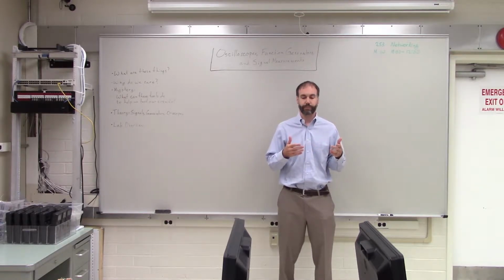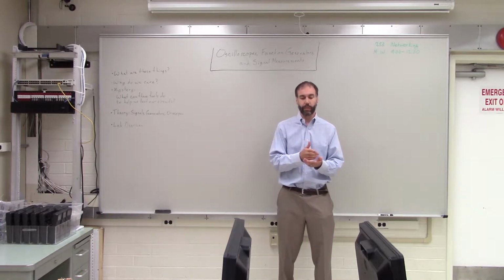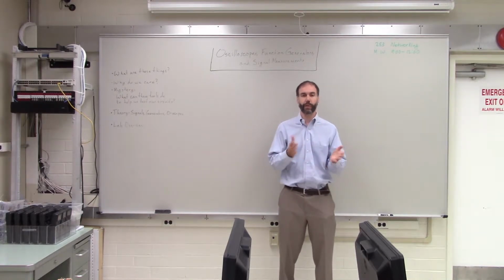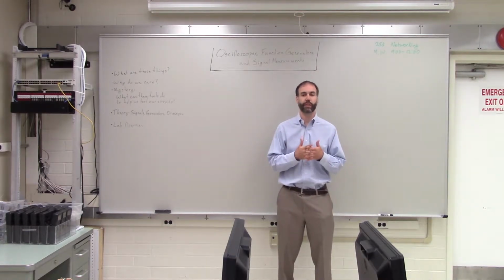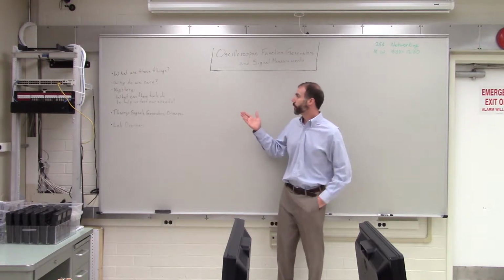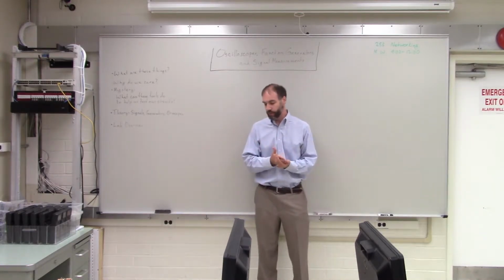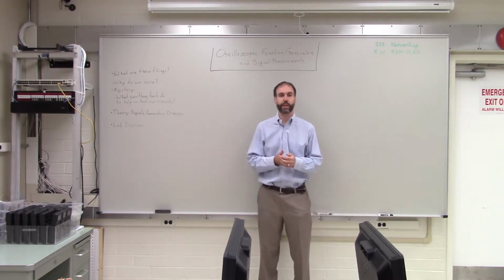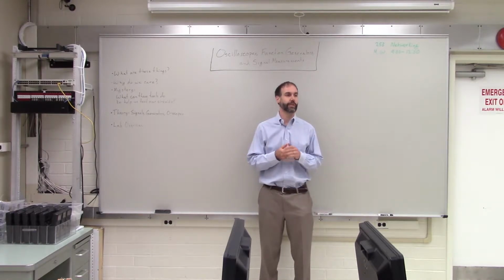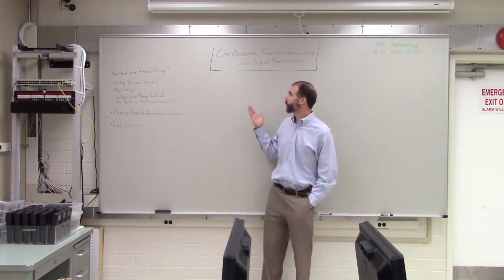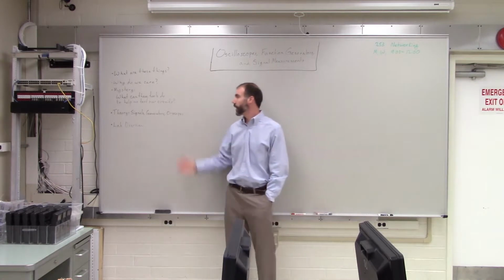If you know that you're supposed to have a sine wave at 50 hertz at this particular point in your circuit, you can put the oscilloscope there and check and make sure that it's actually there, okay? So oscilloscopes allow us to measure signals that change over time, and they can give us very precise measurements of these signals. So that's why those are important. Okay? That's why we care.